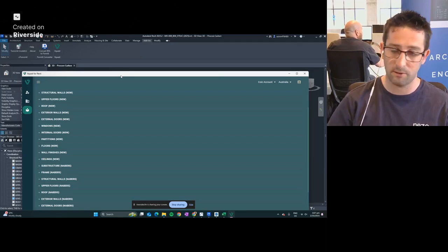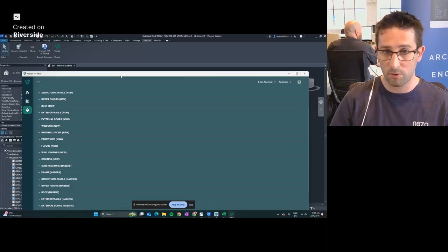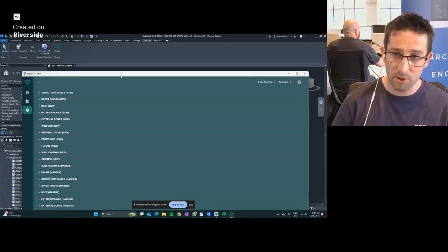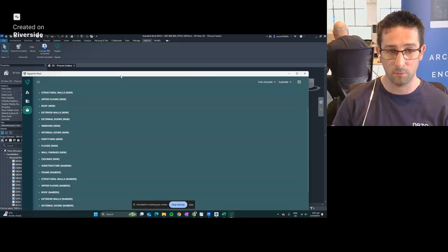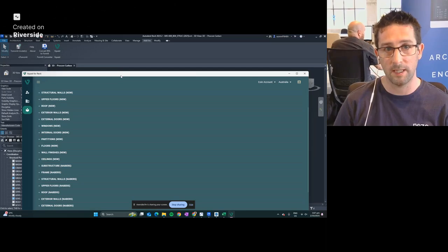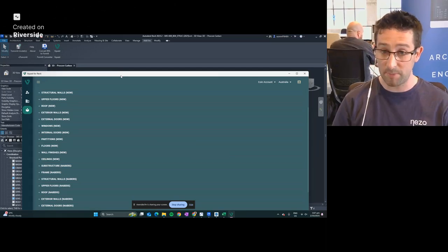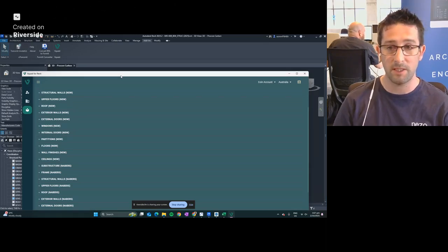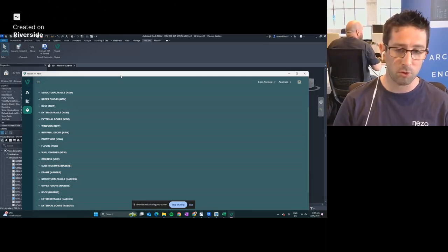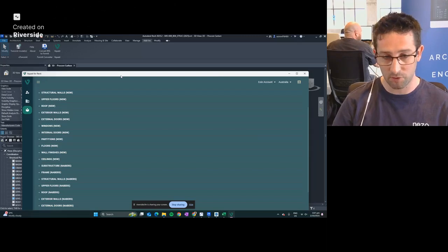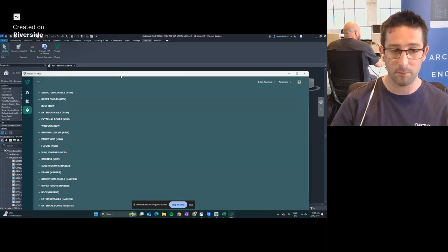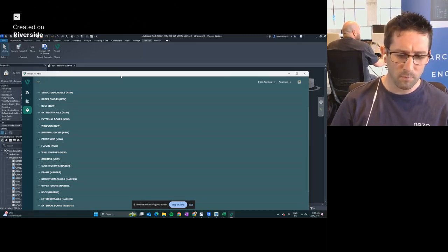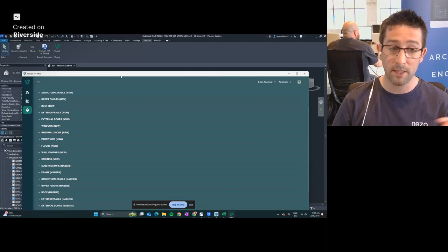Well, for cost, you currently need to go talk to suppliers. For carbon emissions data, NABERS have fantastic resources. You can go to the NABERS EPD list, which is all the environmental product declarations from the various suppliers. There are hundreds and hundreds of EPDs there, thousands in fact, showing you that a cube of concrete from such a supplier has X amount of emissions. They also have emissions factors there as well. And for anything not on that list, you can visit EPD Australasia.